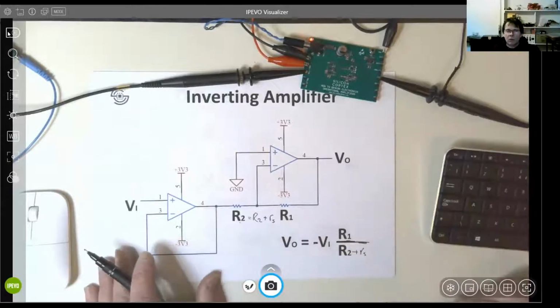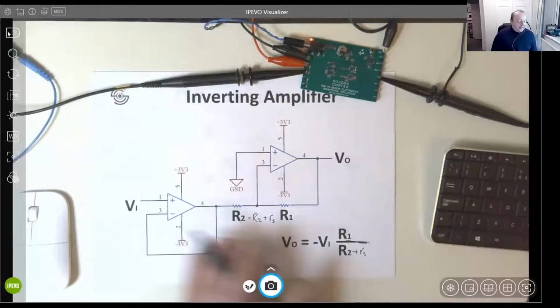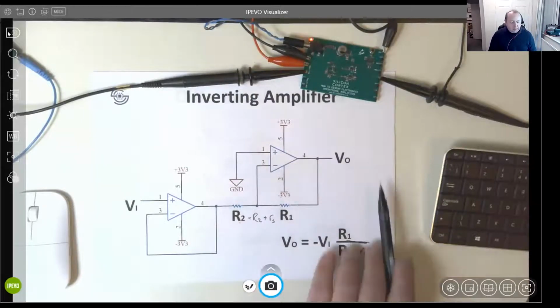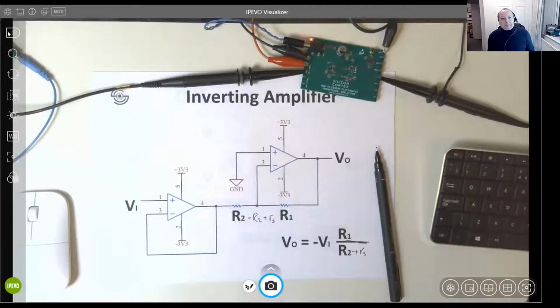Stephen, are you going to cover where we get minus 3.3 volts from in our circuit? I'm used to thinking in terms of ground and V plus or VCC. Yes, okay, right, good spot. So as I mentioned earlier, most op amps, I should say, require what we call a split rail. I mentioned that a little earlier. And when I'm designing electronics, I tend to use ARM cores, which are usually 3.3 volts. So it's kind of my go-to voltage.